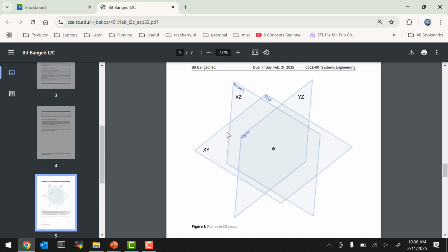as I mentioned last lecture, debugging is going to be a challenge with this lab. You can use print debugging, but you can't actually freeze the code in the debugger as you normally could, even on the Quartus, on the FPGAs. So if you have trouble with communication, one way to diagnose it is to use the oscilloscopes and probe. We have put test points on the board for you. If you look at the bottom of the board, there are little headers that stick out, and there's an SDA and SCL test point. So all you have to do is clamp those test points with the probes of the oscilloscope, turn on the oscilloscope, and you can see what's going on there.